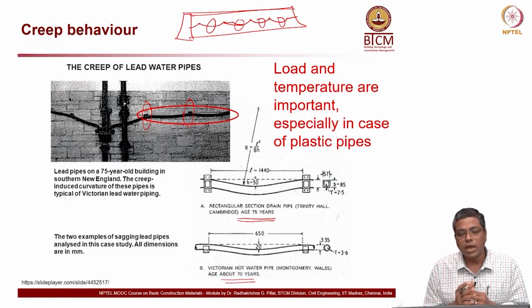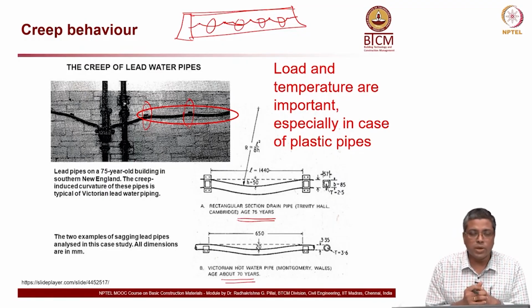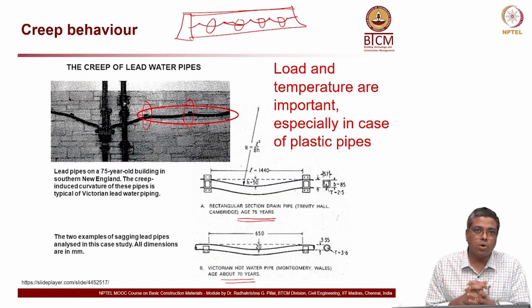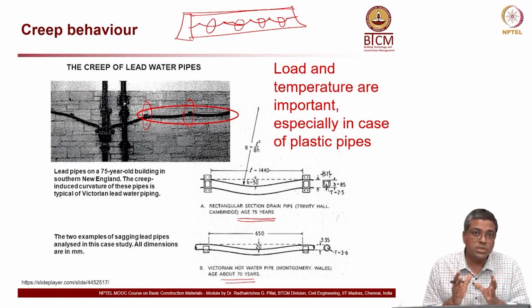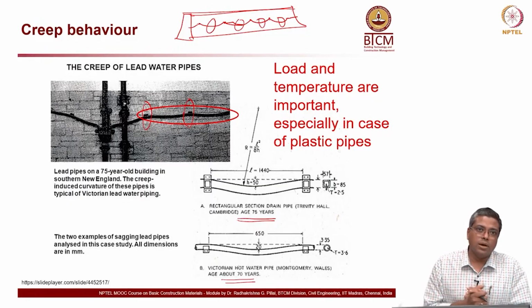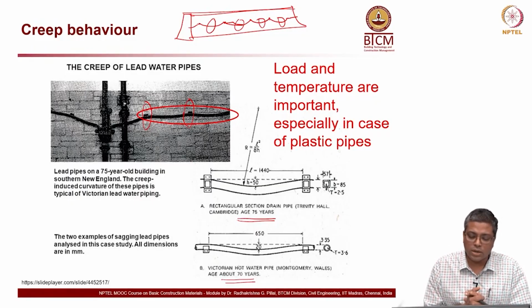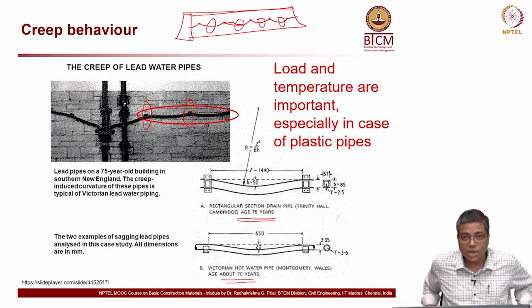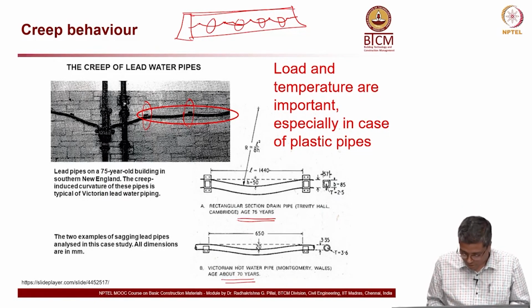Considering our climatic conditions, the temperature is very high, and probably that is making the conduit material very soft. When it is soft, it starts sagging a lot, and then it undergoes creep deformation. So next time when you are on the road, you can look for this, it will be interesting.